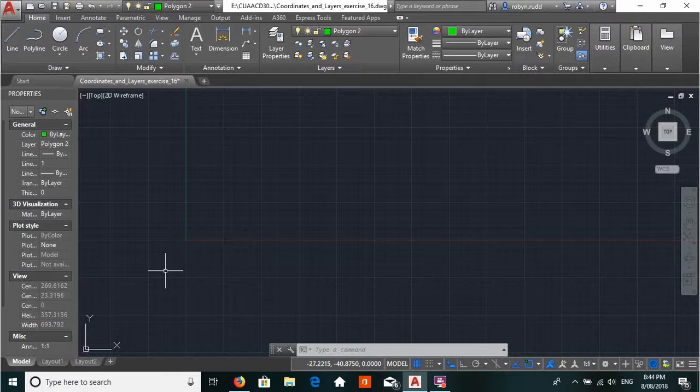Okay, so if I'm wanting to start a point, this is actually where the red and the green line meet. It's telling me that that is the start of 0, 0. Okay, and if you look, wherever I move my cursor, it's telling me the coordinates there on this infinity or model space or black space to draw.